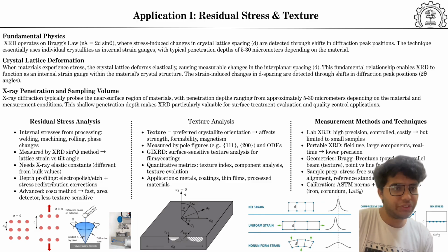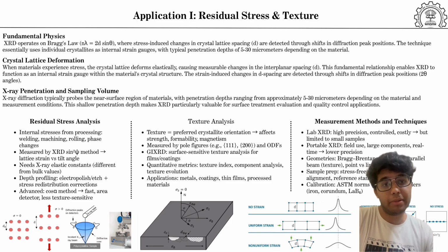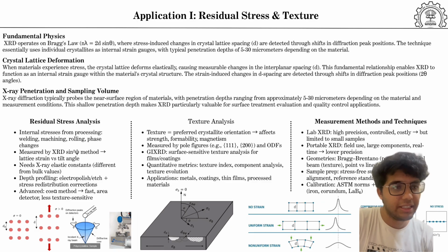Now, when a material is stressed, its crystal lattice deforms elastically. Even very small changes in the interplanar spacing, on the order of picometers actually, can be picked up by XRD. Because the penetration depth is only about 5 to 30 micrometers, XRD is especially useful for looking at near-surface stresses like those introduced by machining, welding, coating, or any such processes.